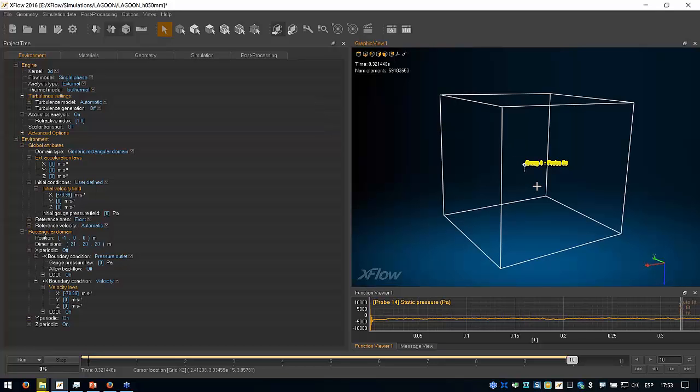It's not a lot of mystery. You don't have a lot of parameters to set up. Very simple to get ready and work with acoustic simulation. So my domain is set up here. We've got the inlet velocity with the plus x boundary here, and flow goes to minus x. That was specified in the LAGOON case, so we just kept the same things.